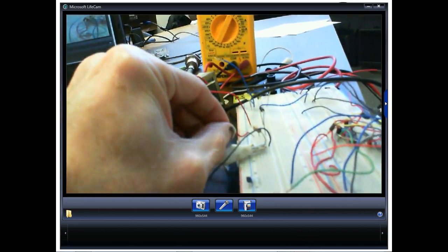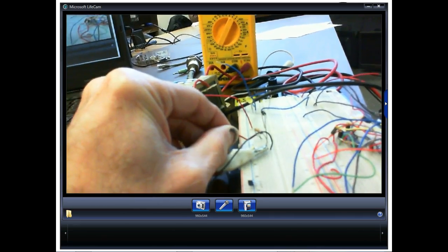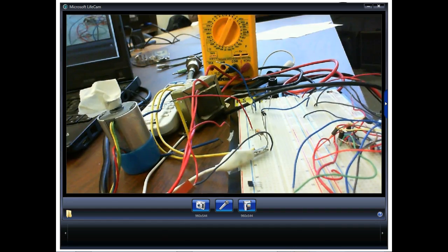Now, if we knew what direction the motor was running a while ago, we would see now the motor's running in the opposite direction. So with DC motors, the voltage polarity you put on the motor determines the direction of rotation. So DC motors are fairly easy to reverse. All we have to do is come up with some way we can electrically switch the leads. We do that usually with relays, which is pretty neat. Okay, so this is a half-wave rectifier. Everybody okay?